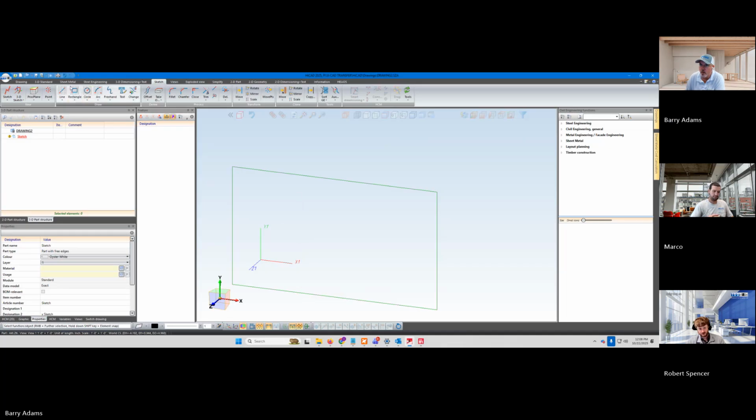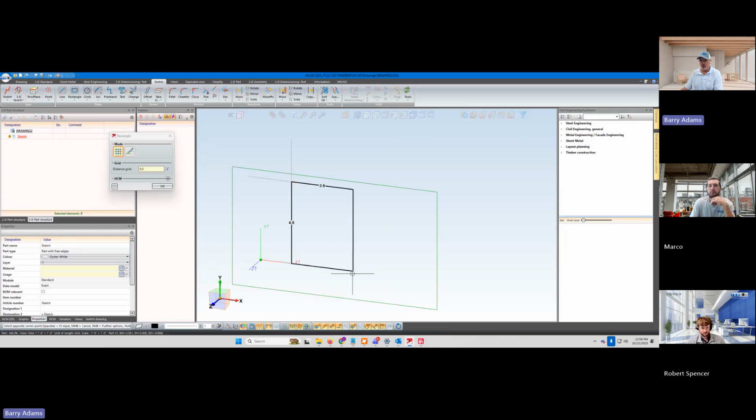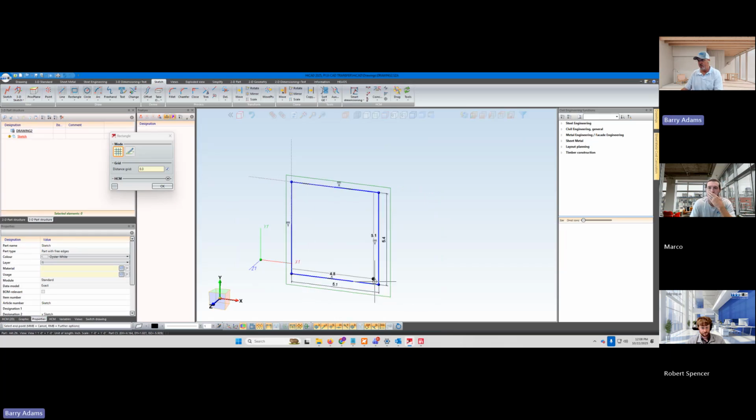Okay. So I want to go to, I did it different the first time. So we're looking for 150 by 150. Select opposite corner, point, and then space bar. If you did the space bar before you clicked a second time, then it would have come up.